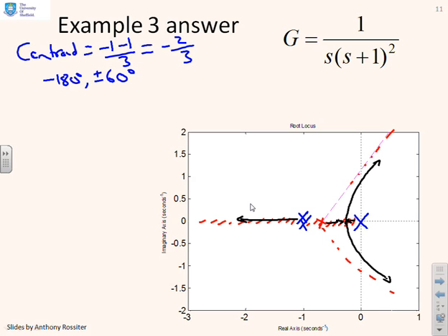And the question was, give me a reasonable compromise between speed and input activity, etc. So if next I draw my line of 45 degrees, there's my 45 degree line, which gives me a damping. I'm going to go for a damping of approximately 0.7, and that corresponds to that point there.